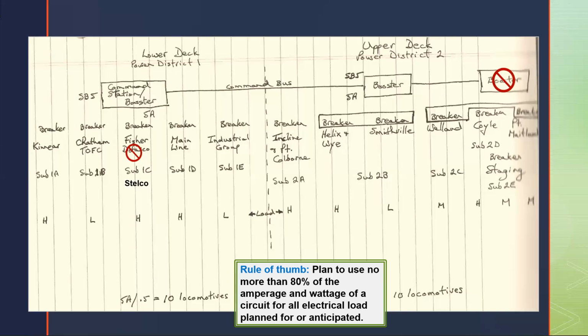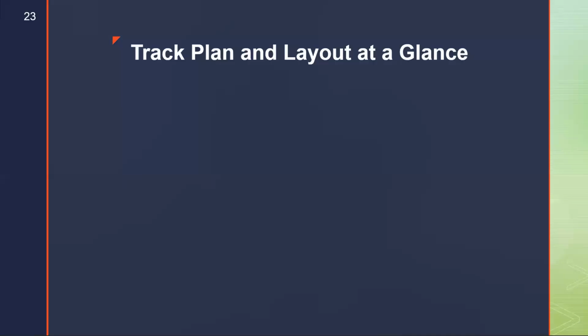So you're not drawing on 5 amps, you're actually drawing close to 4 amps maximum normal usage, which gives you a contingency of 20 should you go over that, and it won't have any adverse effect on your circuit. You may or may not remember in the old days when people would plug too many appliances into kitchen outlets and suddenly start blowing fuses. That's because they exceeded the maximum on that fuse. I don't want to do that on my layout, and pre-planning helped get away from that.